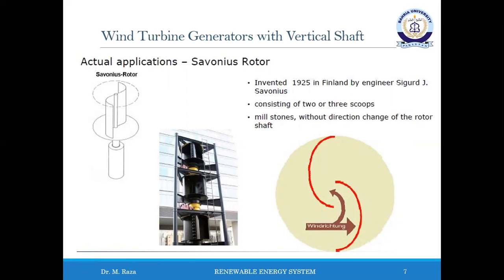The design is simplified because, unlike with a horizontal axis wind turbine, no pointing mechanism is required to allow for shifting wind direction, and the turbine is self-starting. Savonius and other vertical axis machines are good at pumping water and other high torque, low RPM applications and are not usually connected to the electrical power grid.